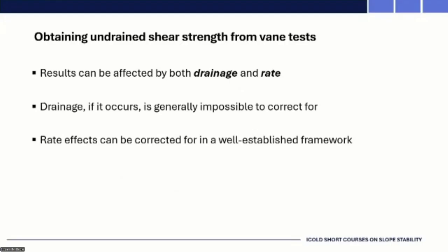Now, a lot of the new vane equipment people have got the drives right at the base of the hole, or just ahead of the vane. You're not trying to turn it from the surface and getting all those twisting effects. So it's possible to do rotations. Some people are doing, I think, 720 degrees a minute, really fast rates to get undrained. In terms of the viscosity, we can correct for that. That previous slide showed you get this kind of linear increase in strength. So you want to go fast, but not too fast, if you can help it.